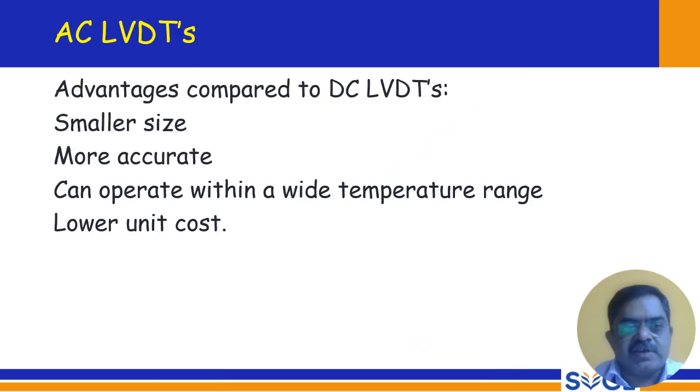So AC LVDTs, advantages compared to DC LVDTs: they are smaller in size, more accurate, can operate within a wide temperature range, and have lower unit cost.